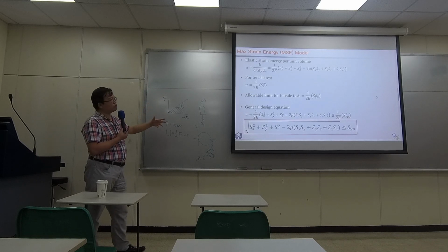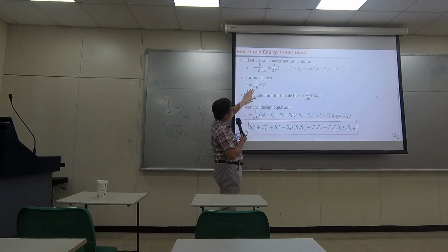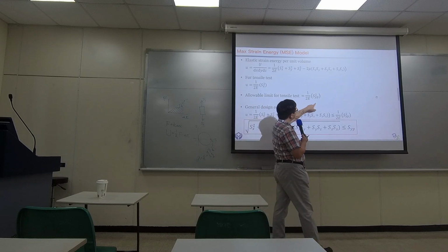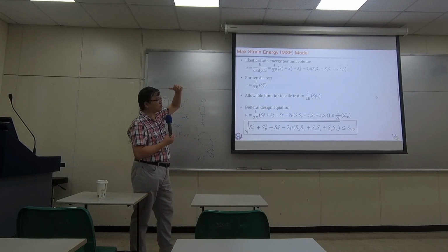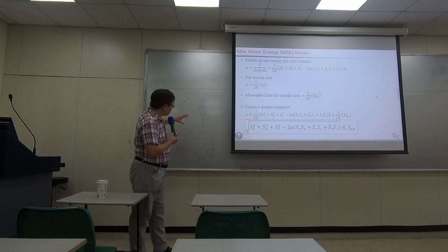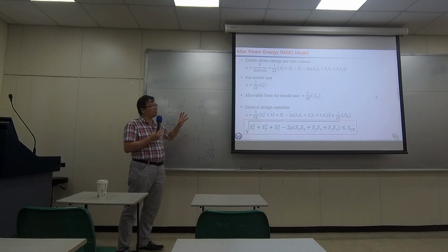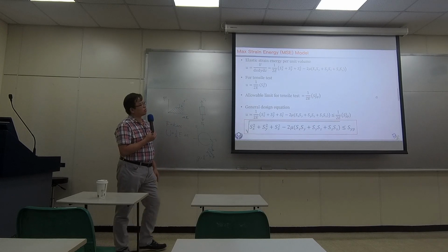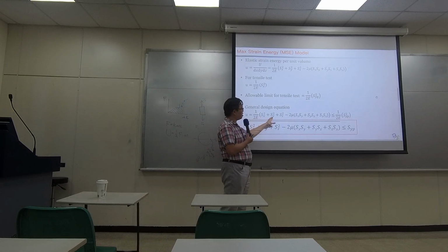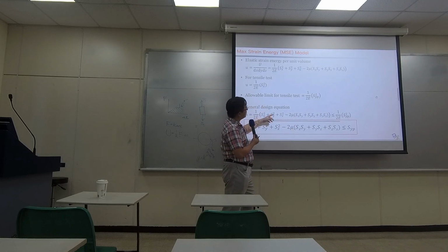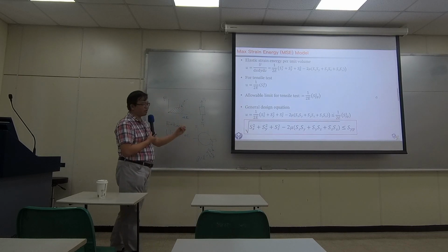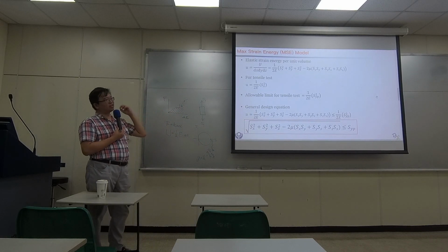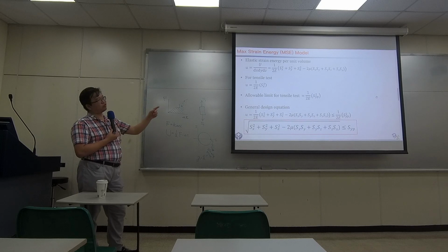So even when we go back to the general equation, we know this should be the limit, because we use the tensile test to realize it. So we use the concept to realize what's the upper limit of this value. So even when we change how we apply stresses, we can have principal stresses everywhere, we still believe this is the upper limit. You cannot find a different concept and explain why this value could be greater.